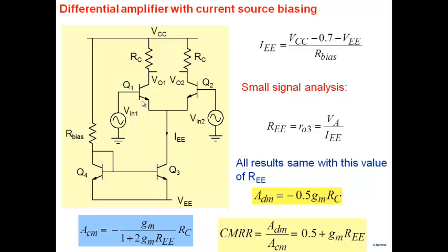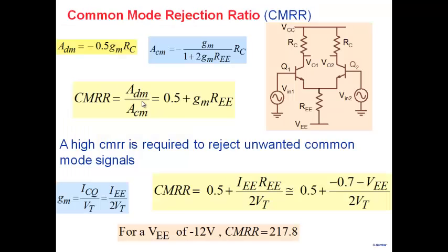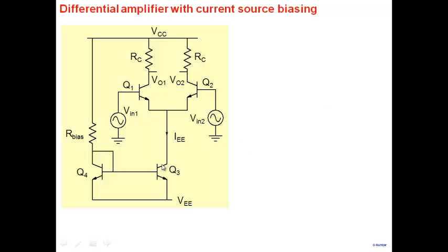Okay? So that's why if you note here, when we went back, we had a resistor here. When I replace the resistor by this one here, you may say, well, you've used one more resistor here, so you've not replaced the resistor. But remember what I said was, we can have one resistor, and with that one resistor, I can bias not just my differential pair, but I can bias many other parts of the circuit.